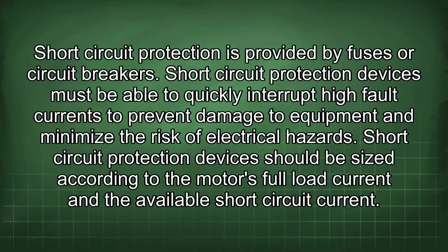Short circuit protection is provided by fuses or circuit breakers. Short circuit protection devices must be able to quickly interrupt high fault currents to prevent damage to equipment and minimize the risk of electrical hazards. Short circuit protection devices should be sized according to the motor's full load current and the available short circuit current.